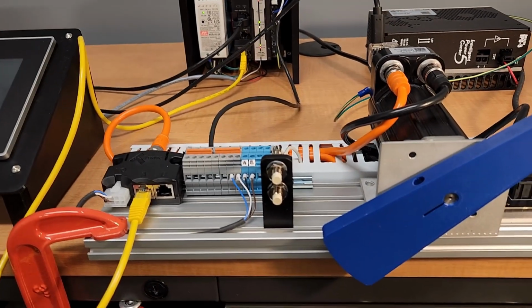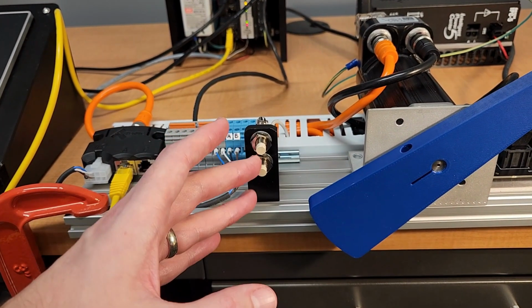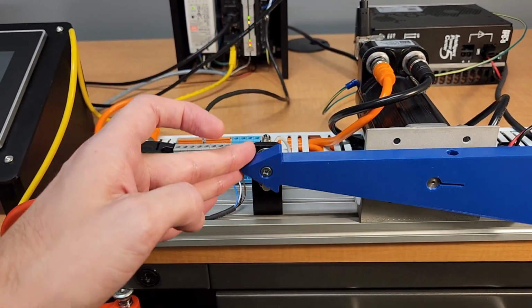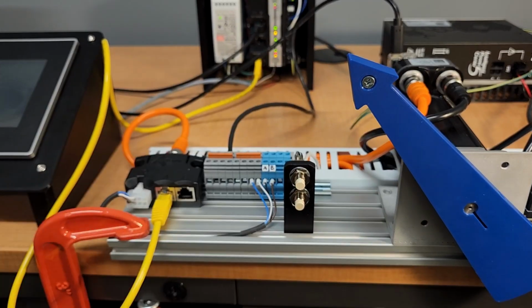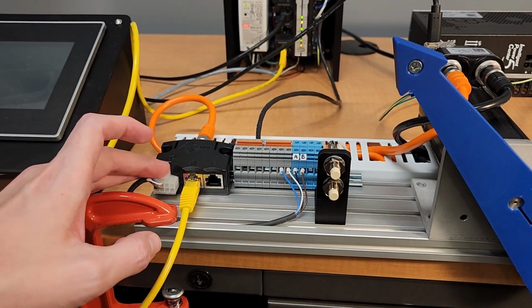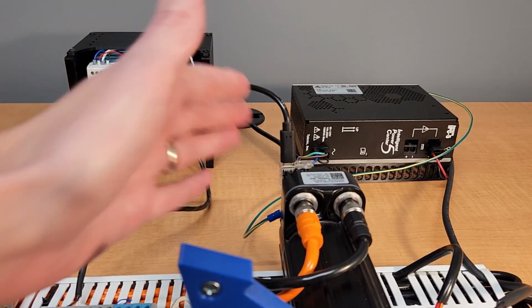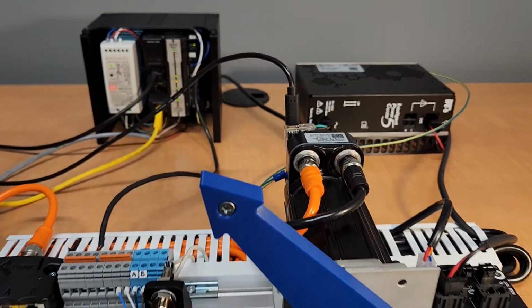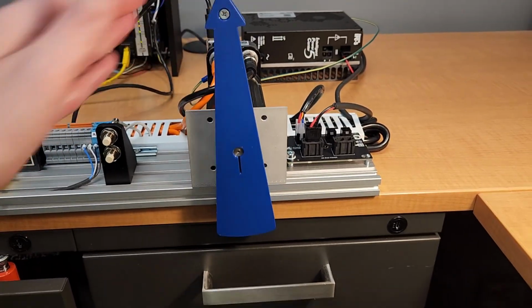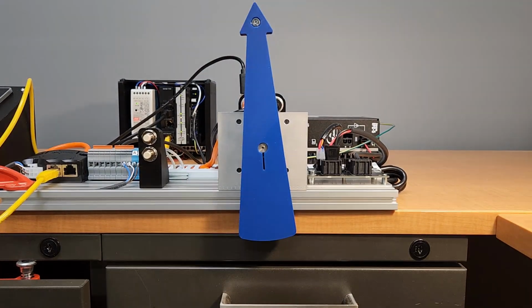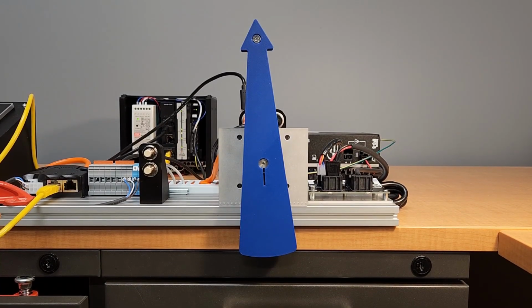For the I/O, I have two proximity sensors that I intend to operate as limit switches, where the drive will stop motion when the proximity sensor is triggered by the screw on the arrow tip. These signals are plugged into the I/O port on the adapter. I also have a USB cable connected to the drive. This connection is used to communicate with Teknic's ClearView software for drive commissioning and troubleshooting. It is not meant to be permanently attached.